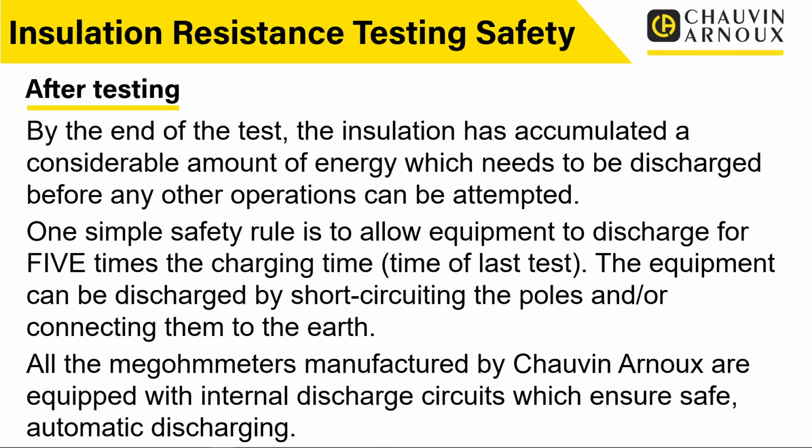If you are moving from point to point to point, you may need to manually discharge them or use a test lead or something to discharge those parts after the test. And also it's important to actually leave the tester connected for a period of time after you've stopped the test to allow that discharge to take place. So just be aware of those things. It's an important safety precaution, often gets missed.